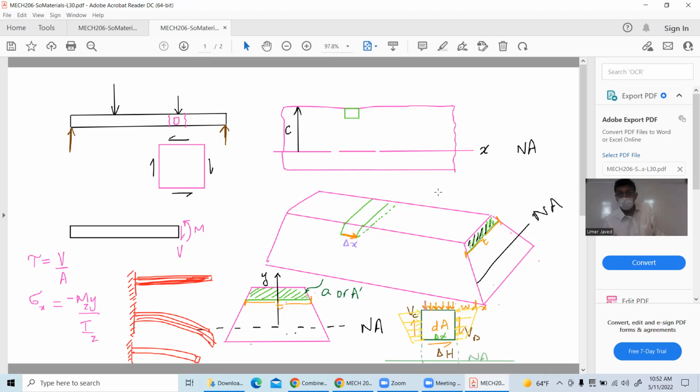I'm talking about the fact that load is being applied from the top and there is shear between the layers. The shear force on the left face here is V, on the C face on the top, V on the D face is, let's say, towards the bottom, I'm sorry. Delta H is towards right, let's say, because if this is clockwise, it gives me towards right. The top surface does not have any shear, of course. The extreme bottom surface does not have shear either. The distributed load is acting from the top, W delta X.